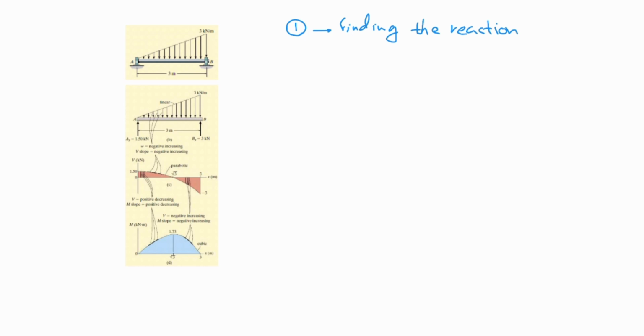For solving these things, what we would do is replacing the joints. Let's assume one of them is like this one, which can apply two forces, but here we have like a slot connection. This rod can slide in this support, and based on that what I would put here is an Ax, an Ay, and for B I just put By because it cannot provide any x direction force.